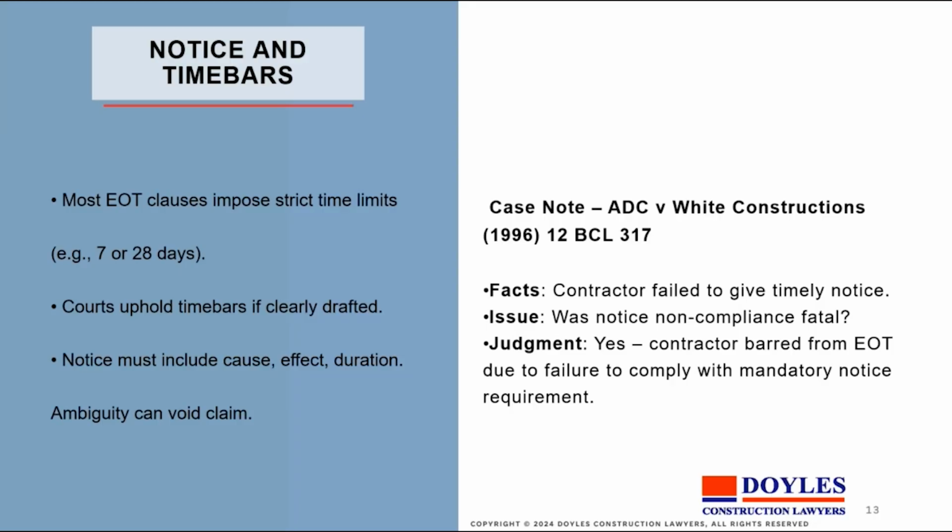So one of the things is you've got to realise that most contracts will put tight timetables on notification, and they often have 2 or 3 steps. That is, you've got to notify when the delay is anticipated, notify when the delay commences, and notify any continuing delay. So all of this should be prepared before you start on site. You should have set up some templates for advising on extensions of time claim and make sure that your programming was sufficient to support those claims.